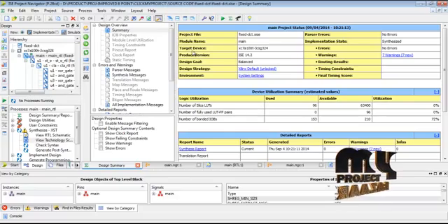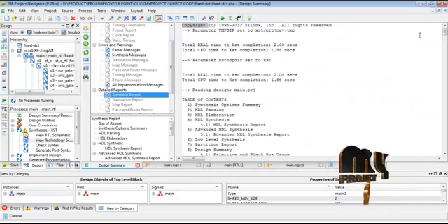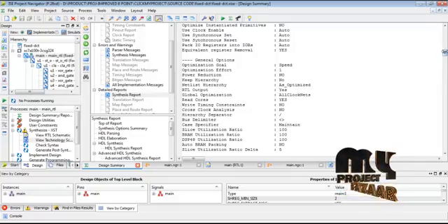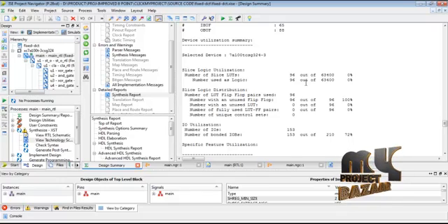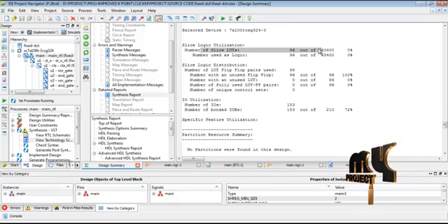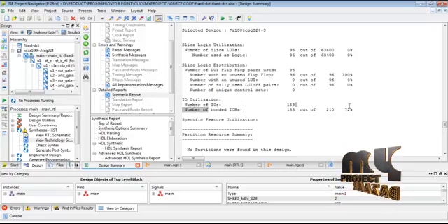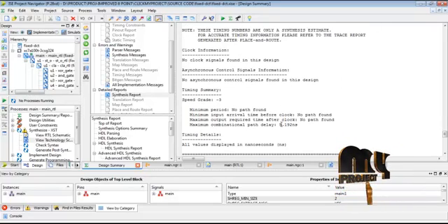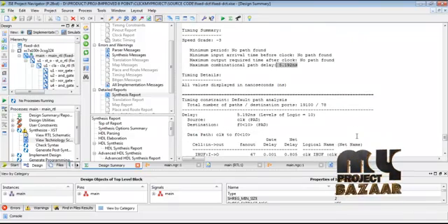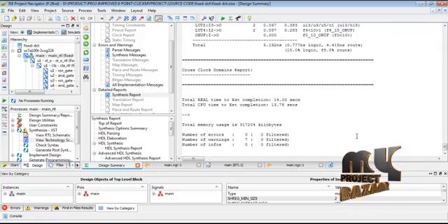Then we go to the design summary, which gives the synthesis report for the required DCT architecture results. This device utilization summary mainly considers the overall slices, LUTs, flip-flop pairs, and bounded input outputs. These results are mainly used for the area of the overall architecture. Then the timing summary gives a path delay of 5.192 nanoseconds for our CSA based DCT architecture.